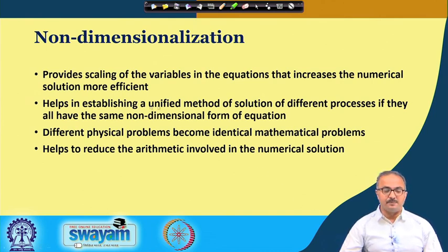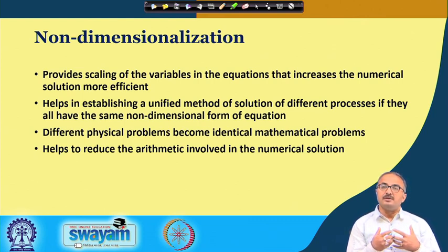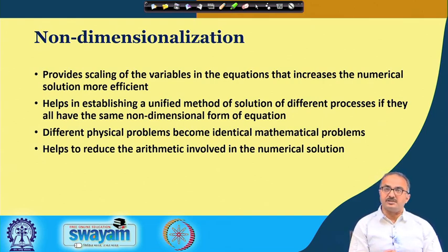First is that it provides some scaling of the variables in the equations that makes the numerical solution more efficient. So when you are non-dimensionalizing the equations, you find that many of the terms may not be relevant for the given situation. So sometimes you will end up simplifying the original equation, and that way your numerical solution also becomes more efficient.